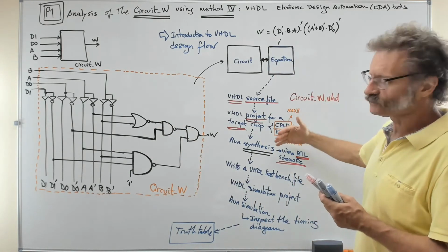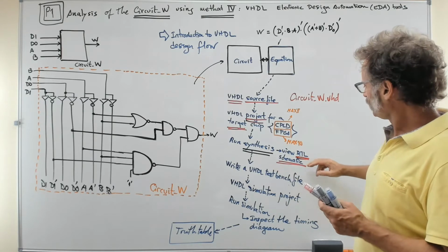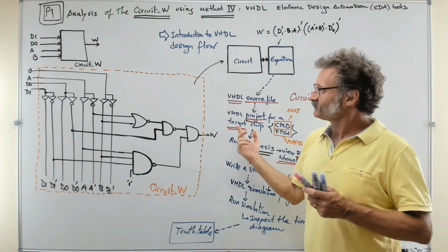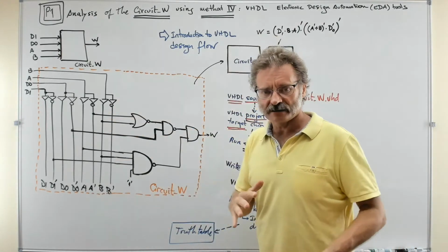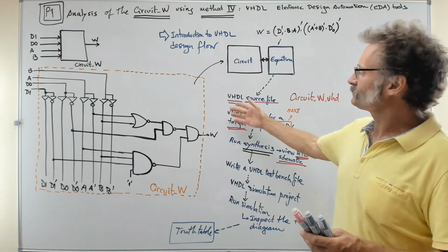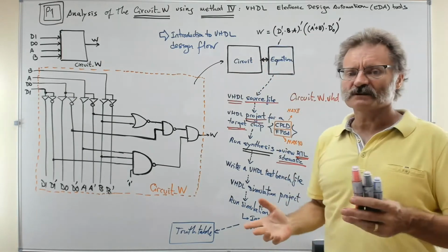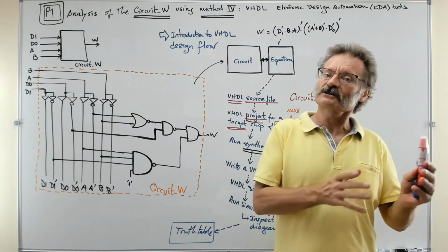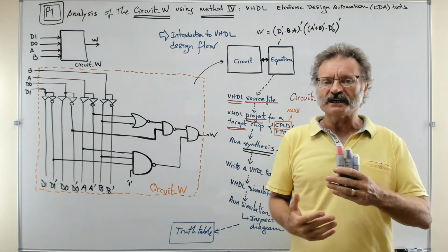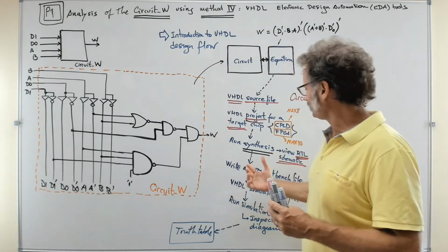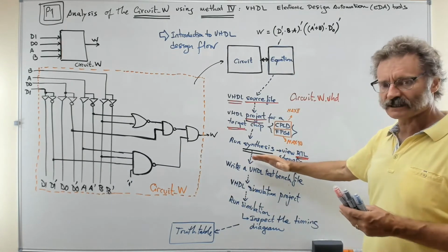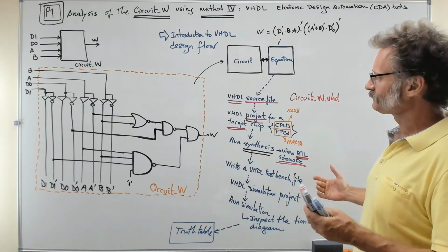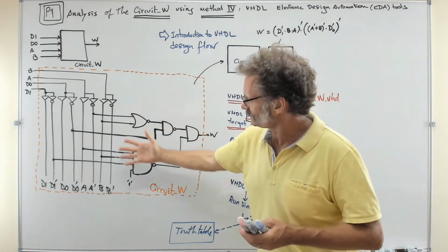We are going to run the synthesis, and we will keep an eye on the RTL to see more or less if what the machine has understood looks like the original circuit from which we have extracted the equation. Pretty much like Wolfram Alpha, when instead of a truth table we do such a thing as a logic circuit. What the machine produces, the engine, is a circuit, right? So here is the same idea. After synthesizing, you will have a kind of schema that you can print and comment on, and keep an eye on it to see if it looks like this.